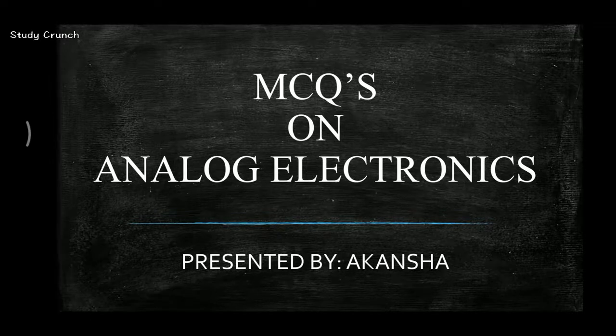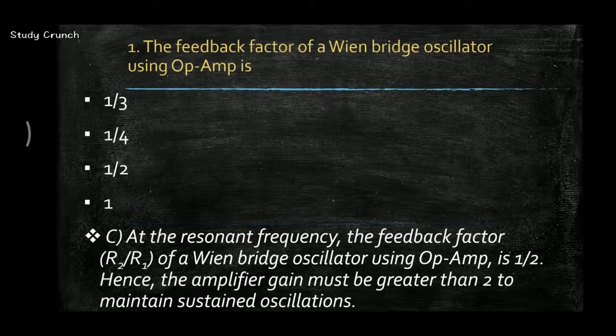Now in the series of MCQs on analog electronics, we'll be starting off with some questions. So the first question is, the feedback factor of Wien bridge oscillator using op-amp is? So the answer is, it is half, because at the resonant frequency R2 by R1 of Wien bridge is half. So the gain of the amplifier must be greater than 2 to maintain sustained oscillations.